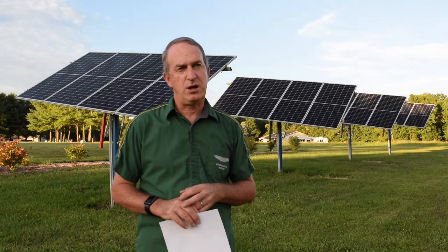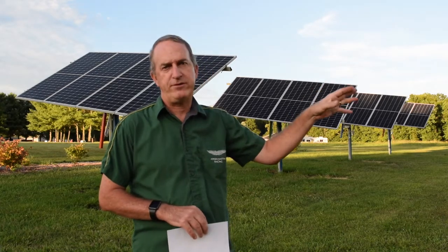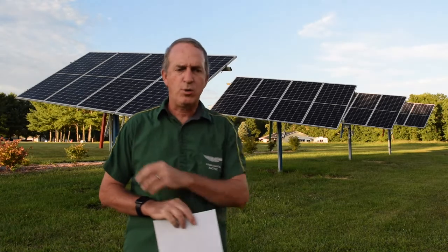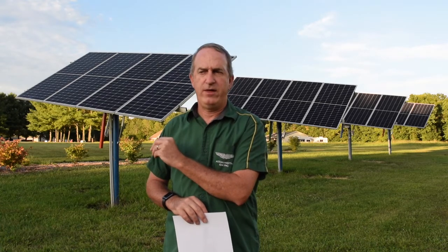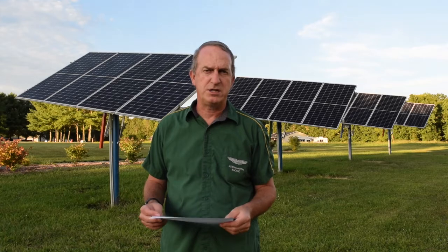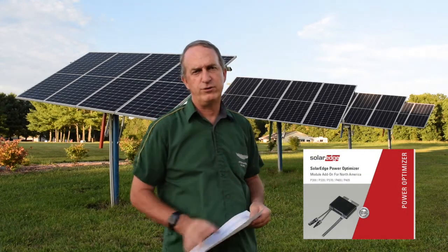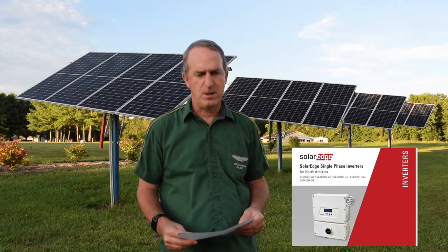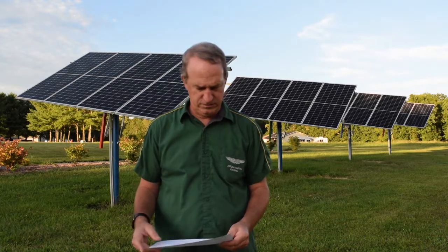The downside is it costs $75 for the optimizer, and then the inverter is about the same price as the Sunny Boy, so you're definitely not saving any money. So obviously the system has to make more power over its life than the cost of the optimizer. The optimizers and the inverters are guaranteed. I think the optimizers are 25 years and the inverters 12 years. So they come with a pretty hefty guarantee. So that's the inverters. That's your biggest decision.